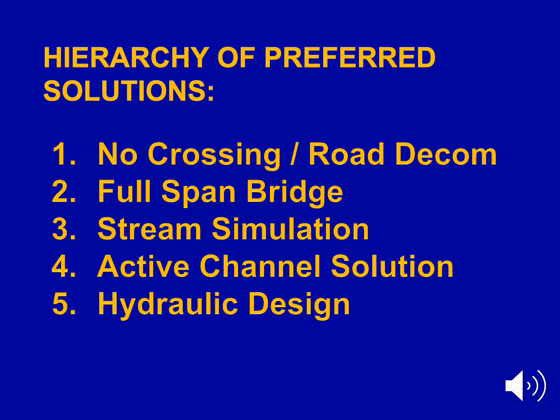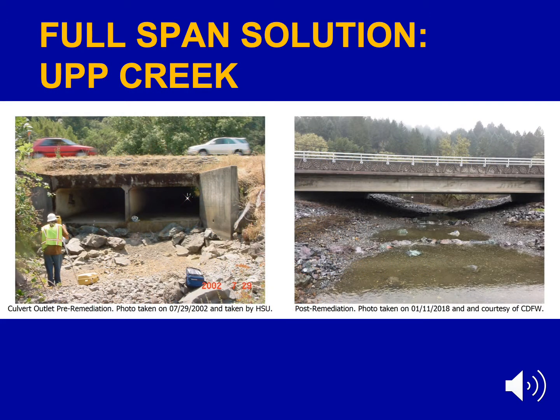natural bottom hydraulics. Then we have hydraulic designs, where that suite of solutions is looking at very closely calculating what your hydraulics are within your crossing, and it's supposed to match whatever the swimming and leaping abilities of your aquatic organisms of concern are. Straight to a few examples and additional detail.